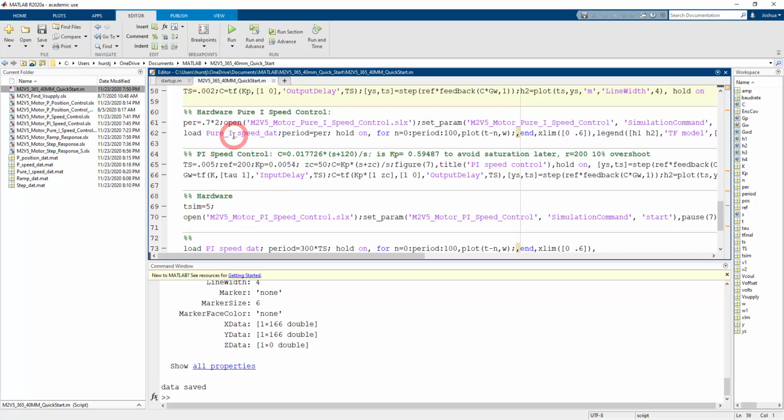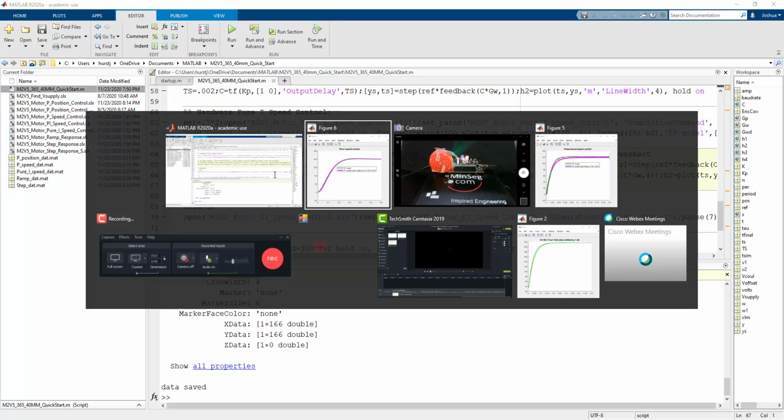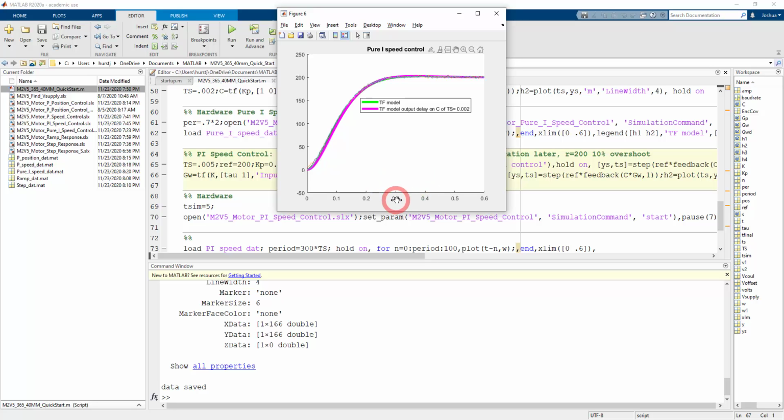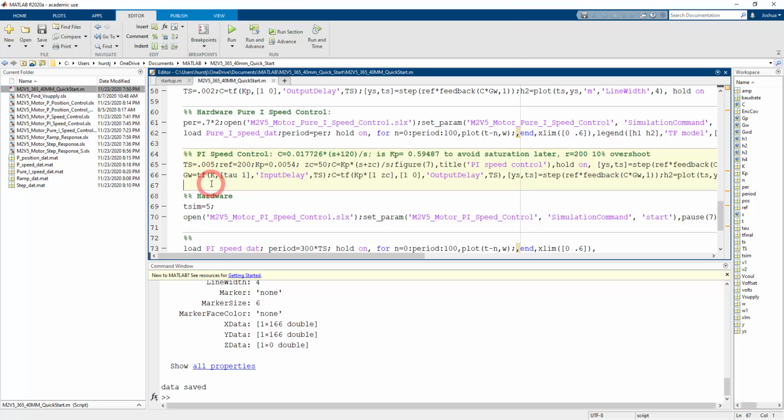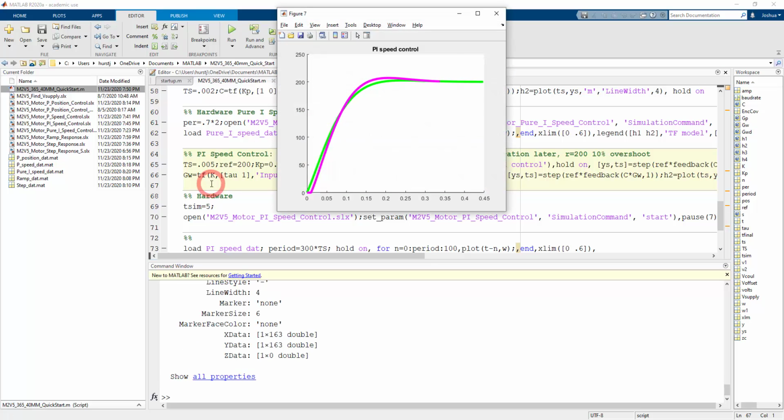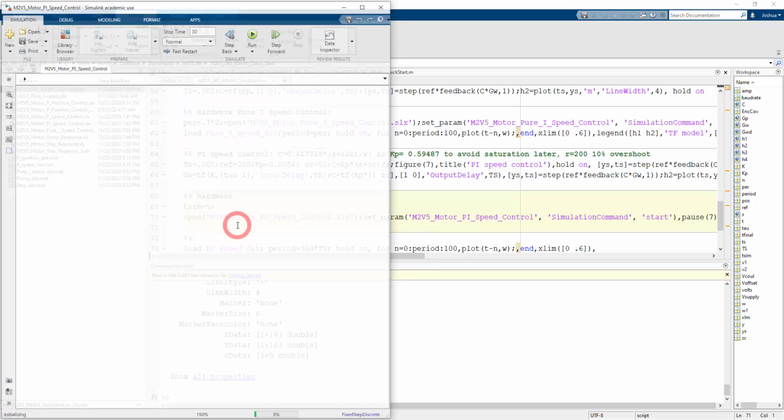Finally, we'll be doing PI compensation. So to try and recover some of this lost speed, we'll add a 0 to the system. That's a PI compensator, pole at the origin, and a 0 somewhere else. So we're going to predict what this PI compensation is. The speed is increased a little bit. So now it's around 2 times slower, instead of 5 times slower, than the uncompensated system that does have steady state error. This is what our prediction is, and we will run the hardware model.